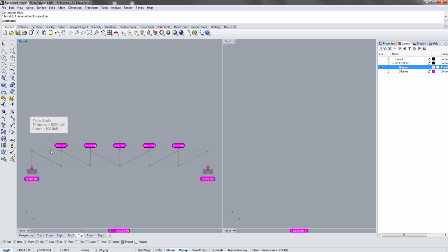But for the sake of analyzing, we are going to assume that trusses only have point loads at these nodes. So for example, you can't really assume that there will be a load in the middle of this horizontal bar, as that would prevent us from doing the analysis. So when we analyze a truss, we always assume that there's loading only at these node points.